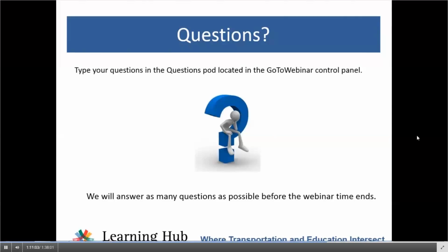The motivation or the reasoning behind using a lower threshold for level of service for roundabouts as opposed to signals is that there's no guarantee for service. So sitting at a red light at an intersection, you know that eventually the light will turn green, and while it's red, you can move on to other things and relax a little bit.